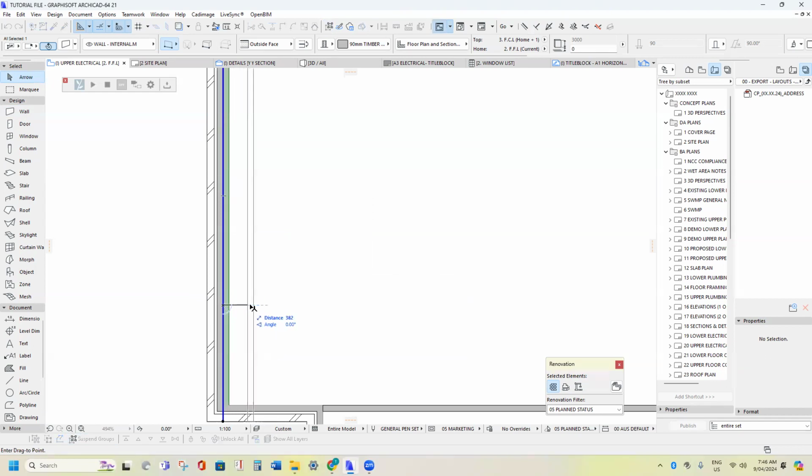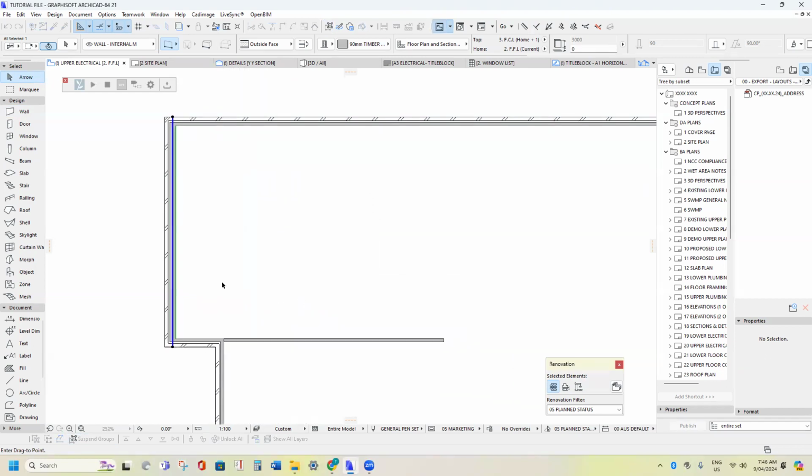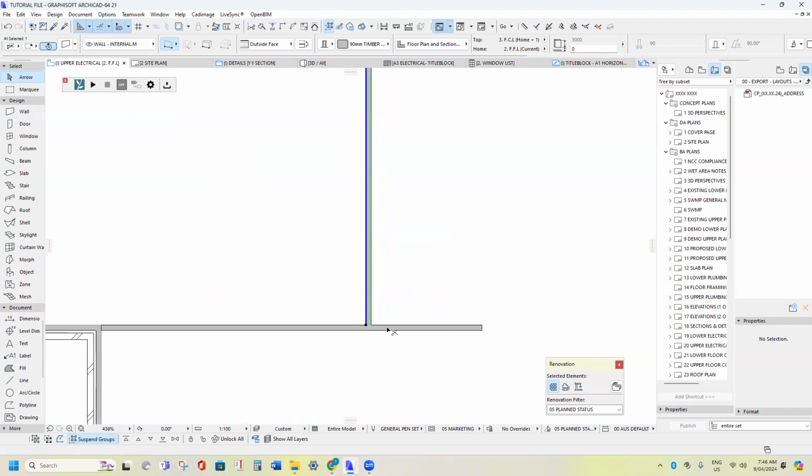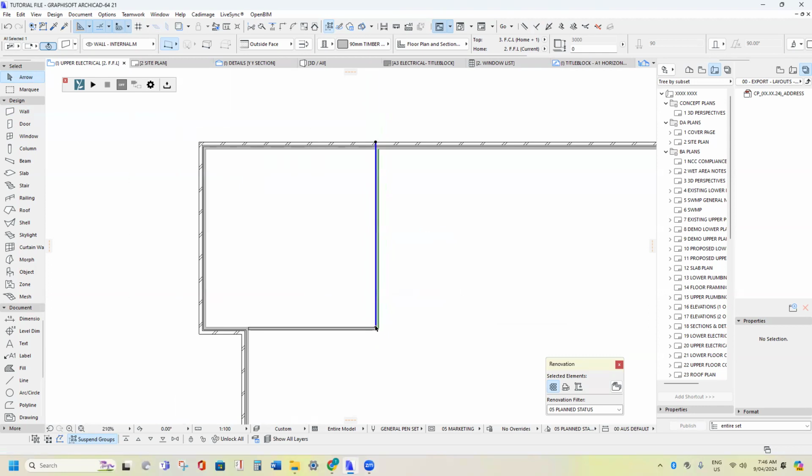So if you press Control D and then click on the wall, and then you hold the Shift key in to drag it out, press R, then you can change the distance, and normally a garage is 6 meters long at least. So 6000, enter, that's your garage now. If you zoom in and press the Control button and click on something, it's going to cut it off. See the scissors showing up? Click, and it's just trimmed it off. Same with this, you can do that as well.